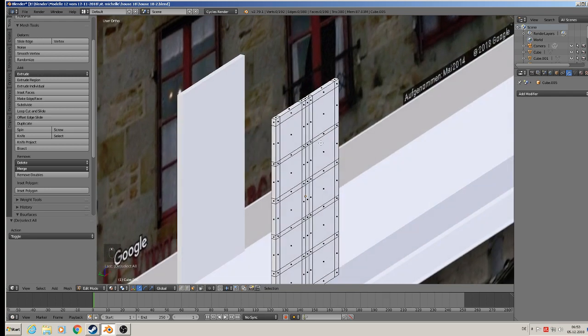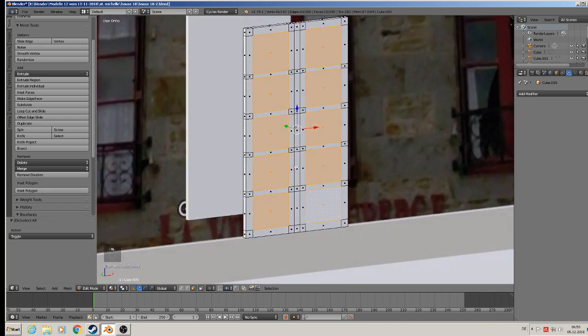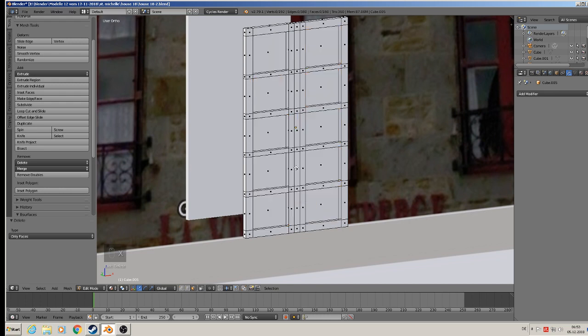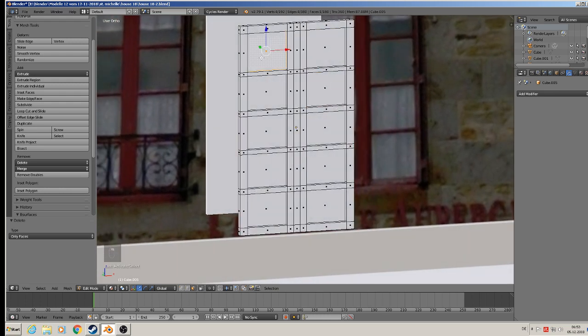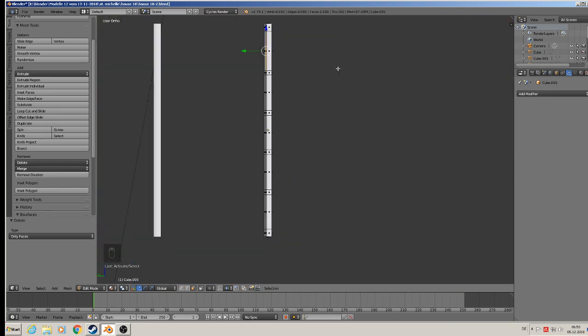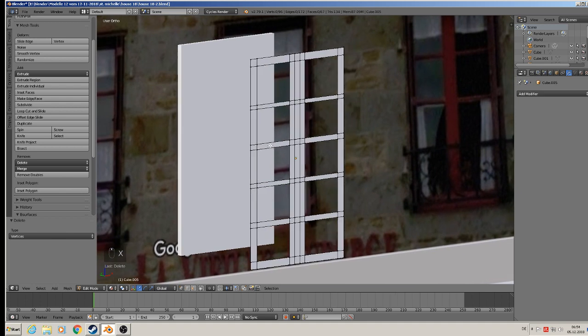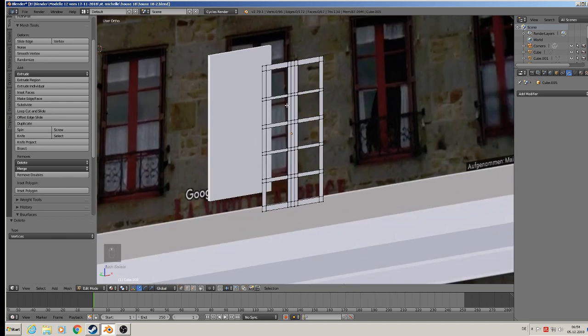So I need here the faces. We can dissolve only, delete only faces. Then I make it the other way. I sort for that. So background selection, wireframe selection. I take border selection with B and take the whole backside, delete them. So that is what we will have and need.